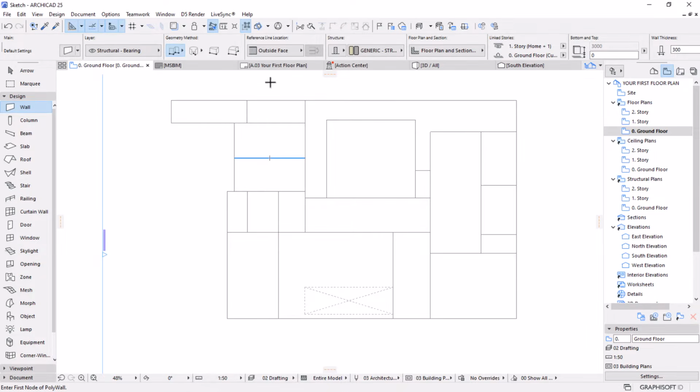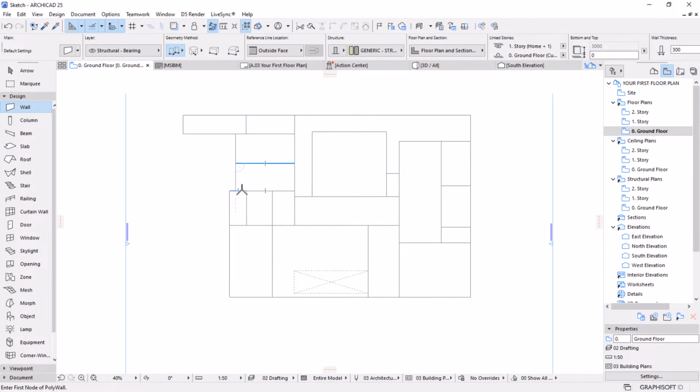Let's hit OK, and then once you've hit OK, we have the geometry method. The geometry method defines the placement of any element. It's either a geometry or construction method. So in this case, we have different geometry methods on how we can place our wall. The first one is the geometry method if you want to draw a straight wall. If you click this arrow, you'll see you can just draw a straight wall that is defined by 2 points, from point A to point B. And then we have the chained method, more like a polyline, where you can continuously draw a wall through many points.